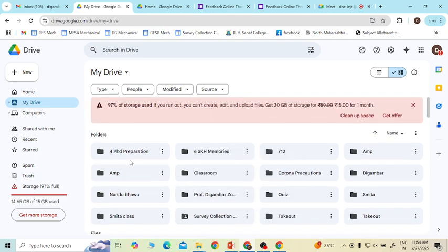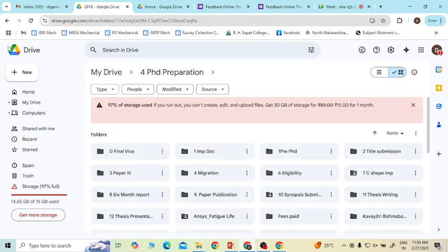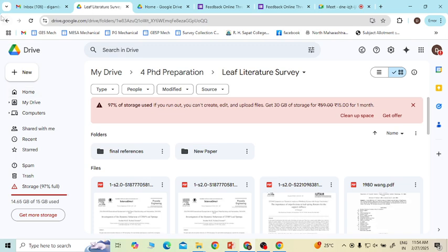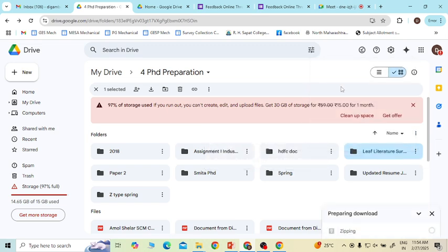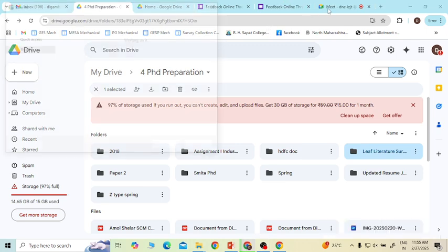This is for digital light processing, which is for photopolymerization. In the earlier case, the laser was used as the source. Here, the process of solidifying is photopolymerization, so accordingly that will be focused. Here you can see we have a digital micromirror device called DMD. There will be a photo source and lenses to adjust the intensity, and one controlling mechanism which will guide the focusing of the light. This is the digital light processing technique.